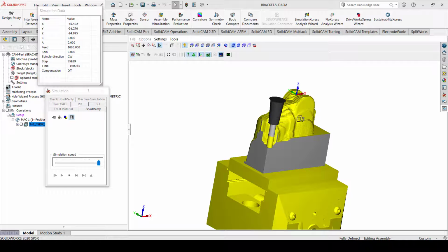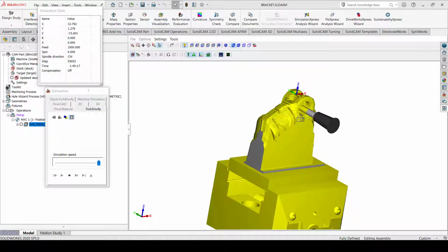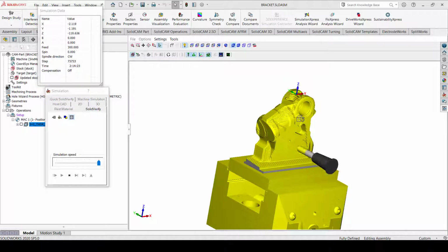And whatever then remains is passed on to the other direction by means of updated stock. So all these stock calculations are done automatically by SolidCAM and then passed over to the calculation to take the updated stock into account and then machine it.